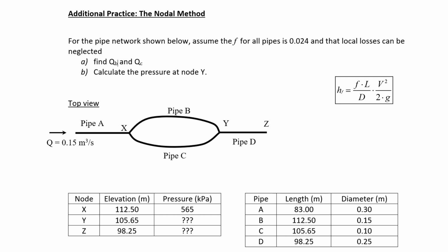I was surprised at how many students reported to me that the head loss would be different through the different routes, because the whole governing law is that the head loss is the same regardless of whether you go through one pipe or the other. Remember the ski resort example, where it doesn't matter if you take one path or the other, the elevation difference is the same when you start at the same point and end at the same point.